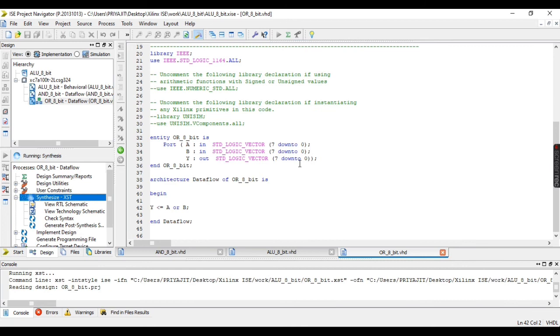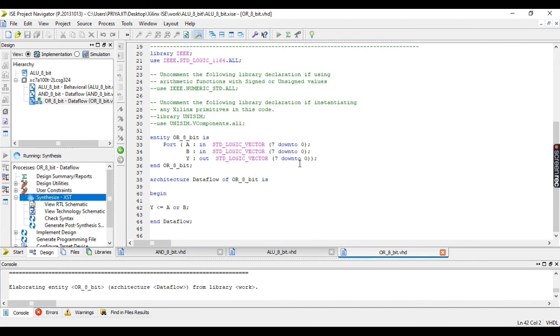Why? Because otherwise if some error exists in our design, then in future when we will be calling these submodules one by one in the main module, the top level module, and some error occurs, it will be very difficult to find out from which submodule this error is occurring, or whether the error is not from any submodule but from interconnection.